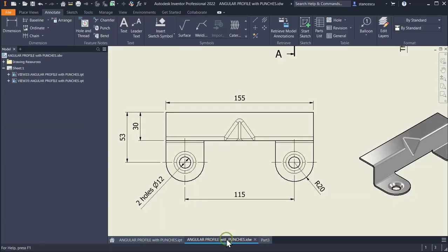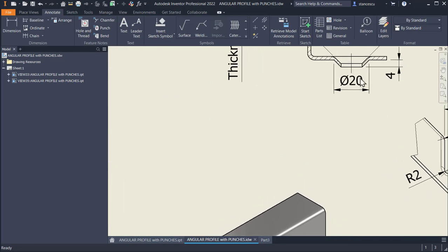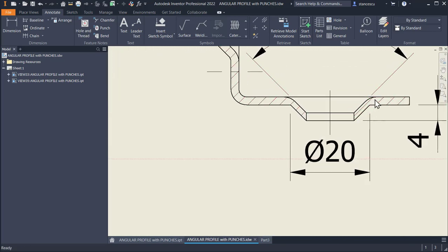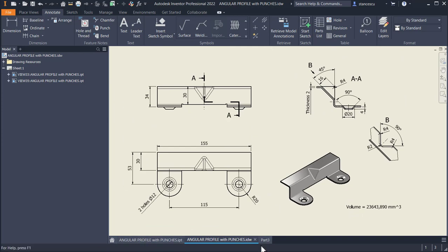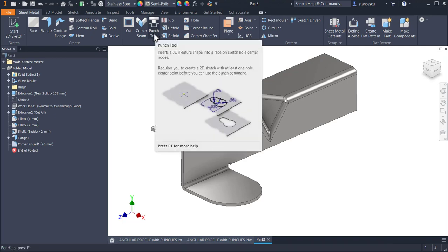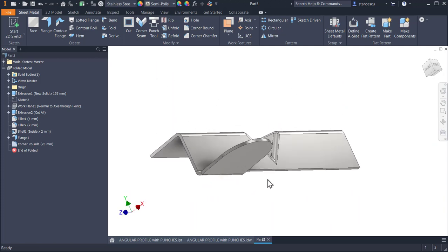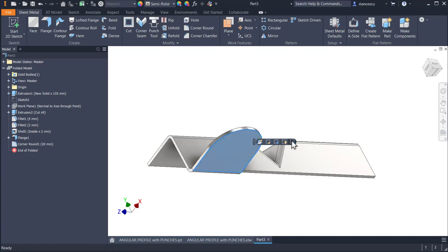Now what? Well, you see here a special configuration. We used revolve to close contour about an axis like this to obtain this. Now we use another tool, which is punch tool, but we have to create a point for this, for applying this tool. The point is at the bottom on this face. I select this face, I make it sketch, I go back and I have this point.